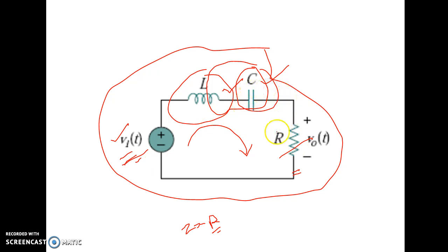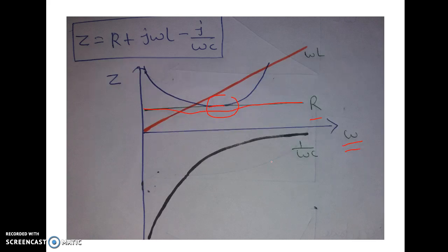So basically, whenever this circuit is purely resistive, we say that the circuit is in electrical resonance. And when this series RLC circuit acts like a purely resistive circuit, that is, when omega naught equals 1 by root over LC, then the circuit is purely resistive, so we say that the circuit is in resonance. Okay, here resonance does not mean the chemical bonding, which is different in chemistry. Here in electronics this is different.